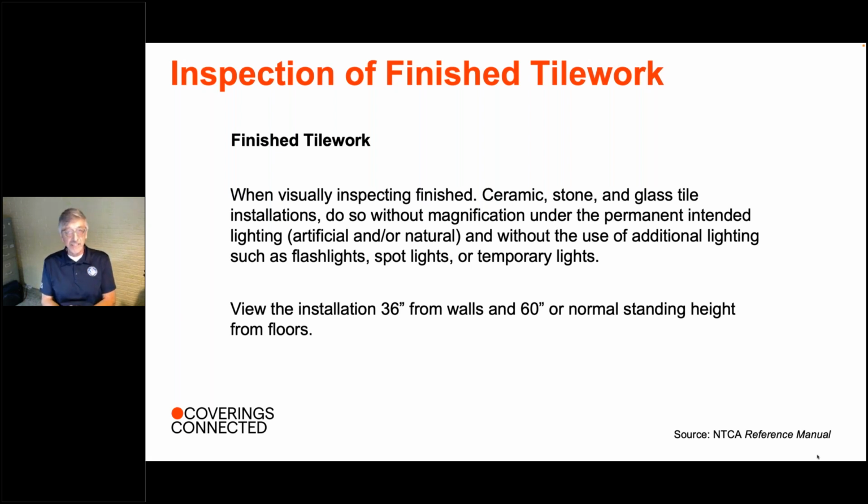When you inspect an installation, don't get down on your hands and knees. Don't get right up next to that wall. Don't use a magnifying glass. Don't use a flashlight or a spotlight. Stand at normal viewing height and look down with the normal lighting conditions and look at that terrific installation. Look at that wall from a normal viewing distance in natural or intended lighting. Don't use a flashlight. Looks great, doesn't it? That's how we inspect finished tile work.